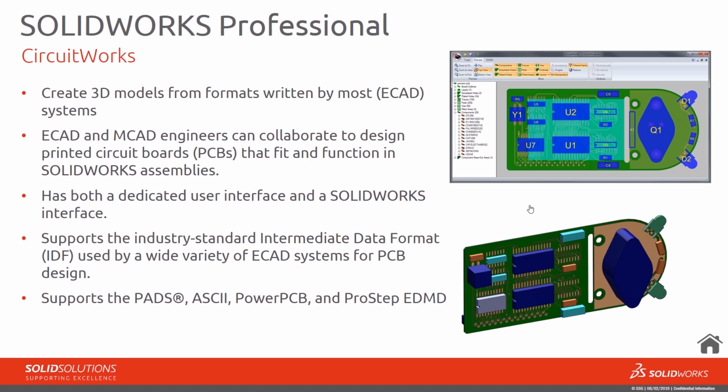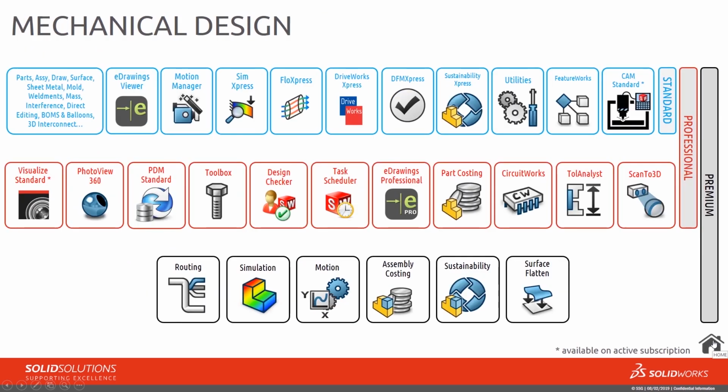So IDF is like a standard PCB format, but we can also support others such as PADS, ASCII, PowerPCB and ProStep EDMD as well. So those are all formats that are supported by CircuitWorks. So again, it's just a way of collaborating really between ECAD and MCAD designers. So that's included in Professional as well.